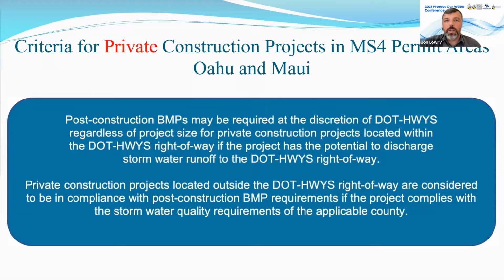And the good thing about private projects, I guess for the DOT side, is that if you're in an MS4 permit area, either on Oahu or Maui, you're most likely going to trigger, almost like 99% of the time, the city and county's requirements. So if you trigger the city and county's stormwater requirements and you comply with their requirements, all you have to do to comply with DOT is submit that report showing that it's been approved by city and county. And we will consider that being in compliance with DOT's stormwater requirements.